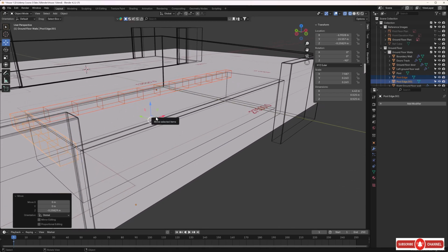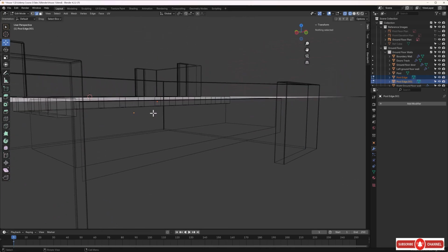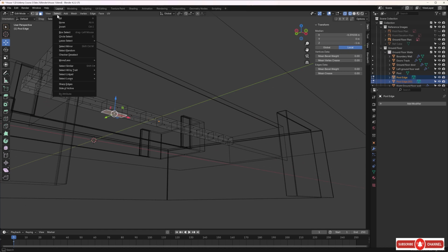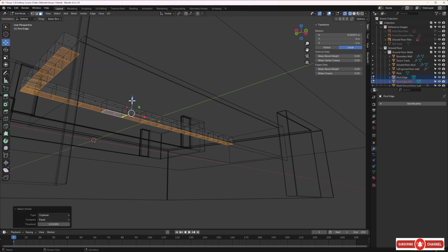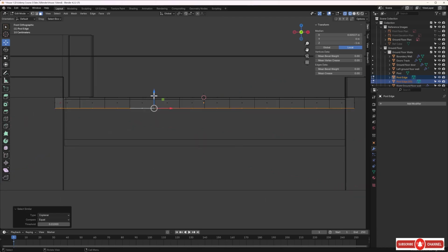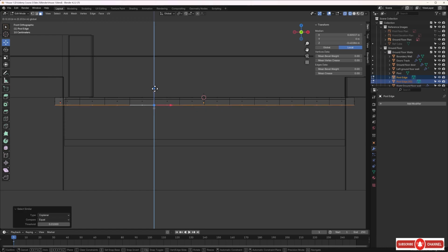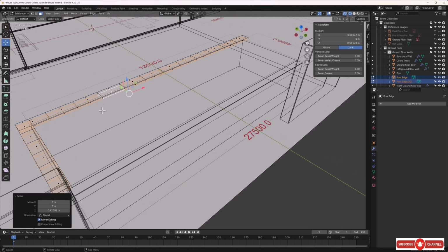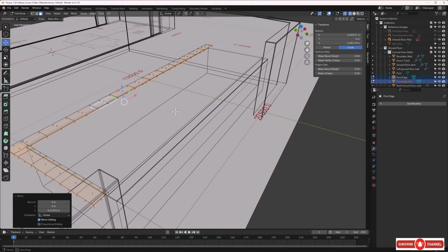And let's tap into edit mode with both of those and press 3 so we can select faces. And I'll just select this one, and then we'll go over to select and select similar, and let's select coplanar. And now let's press 1 again on our numpad to get that orthographic view of the front, and now bring that up to get a thickness for these edge tiles. And I think about that should be good.